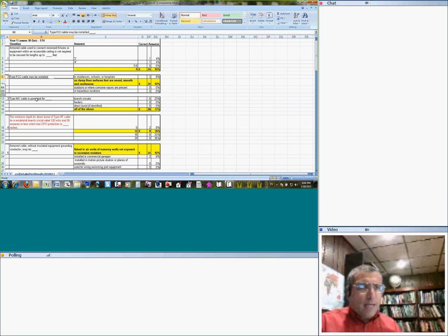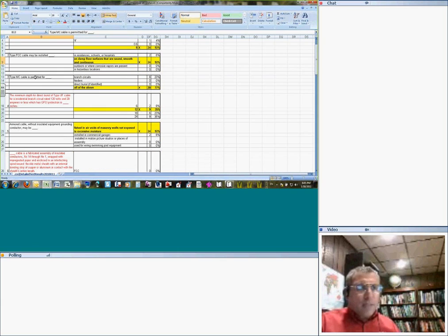You got it right. The second one, FCC cable. You read all this stuff. They don't want you to use it in residential or hazardous locations. The closest to the accurate answer is basically on damp floor. Damp might have confused you. It's not wet, it's damp floor, but it's smooth and sound, smooth and continuous. So type FCC can be installed on damp, smooth, and sound floors. Most of you were right on this too.